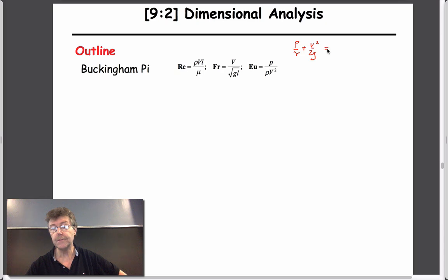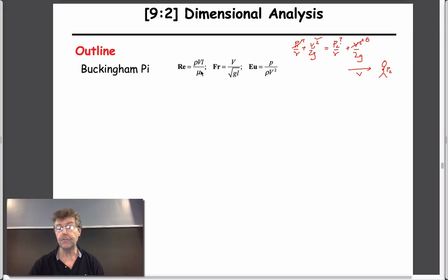and if you write this upstream and downstream, then you know that if you're looking at the forces that are applied on something, like someone standing here, and a velocity that is applied at them, then the pressure that's applied on that person you'd get by just defining the upstream pressure as atmospheric, the downstream pressure we don't know, the upstream velocity as something, the downstream velocity as 0, and you'll end up with the ratio of those, which are really the components in the Euler number.